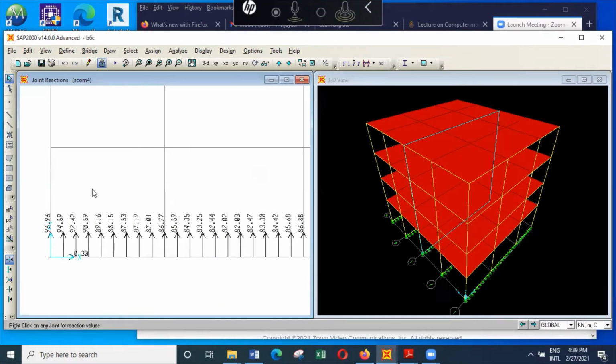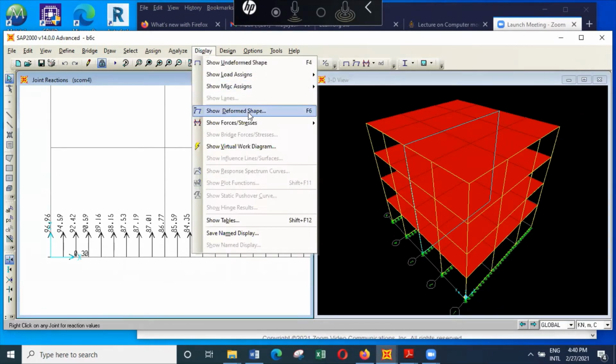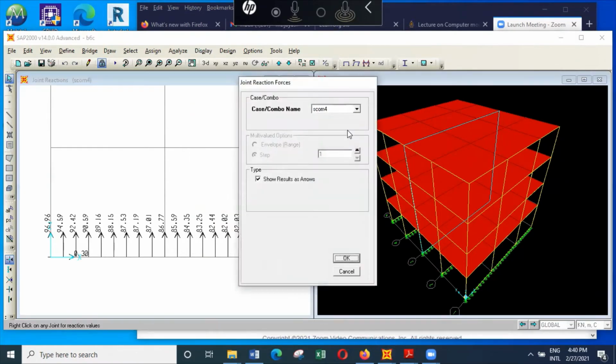You can see here the values are lower, so they are within the limits, something like 96 divided by 0.5 divided by 1.8 gives something like 106. So these values are okay, 107. And then here also the stresses are lower. Then I can ask it to display joints, comfort as well.